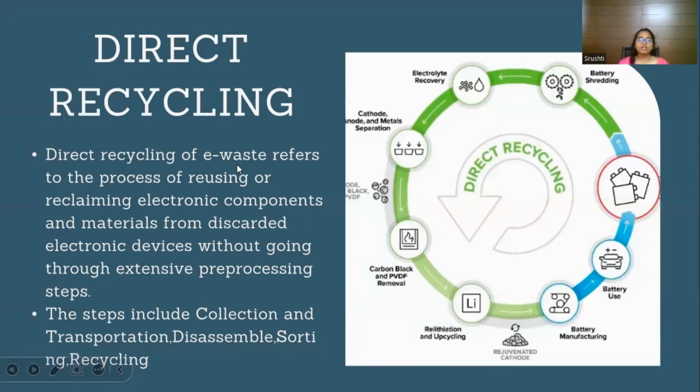Direct recycling of e-waste refers to the process of reusing or reclaiming electronic components and materials from discarded electronic devices without going through extensive pre-processing steps. This includes collection and transportation, disassembly, sorting, and then recycling the products or the components which you find. This image right here shows us the different steps which are included in direct recycling.